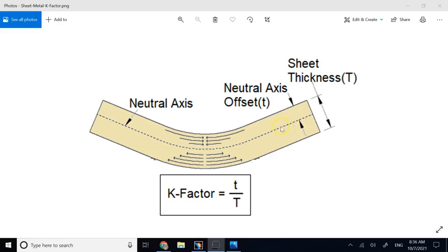Well, when you bend something, based on solid mechanics that you hopefully learned, if you do a cross section on the material, a portion of the thickness of the material will be stretched, a portion of it will be compressed. So the portion that is stretched is having positive normal stress. This part has a negative or compressive normal stress, and because the stress cannot change discontinuously, it has to change continuously. So it goes from positive numbers to negative numbers.